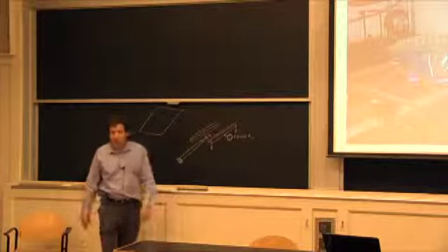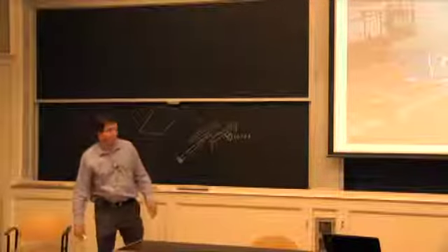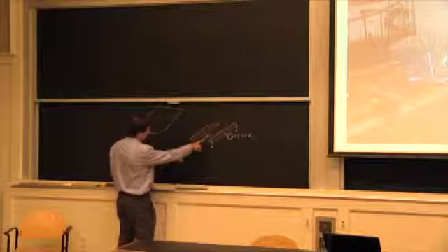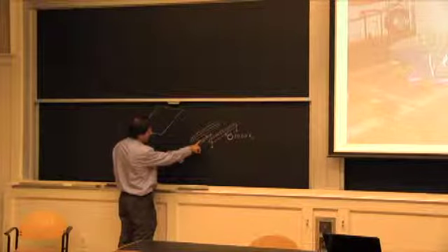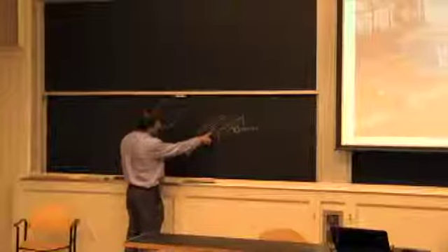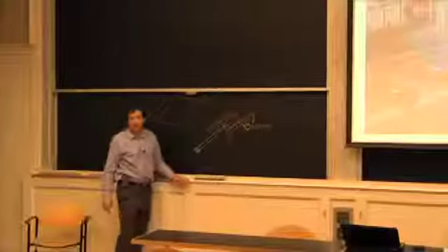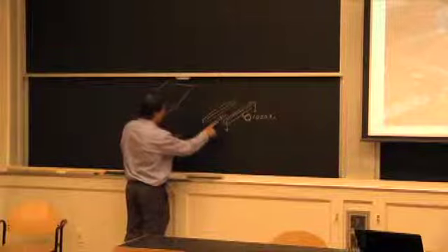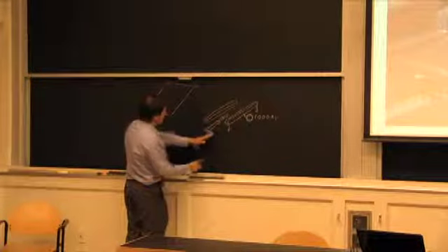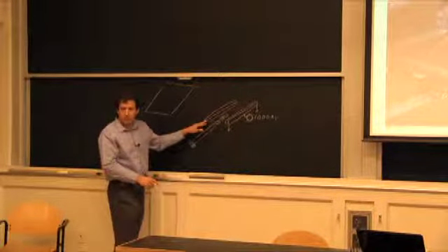The reason why I didn't get concerned with the overload is in this connection here, I did not have welds on the tension side. I designed my connection so essentially this member was sitting under the cross member and the welds were on the compression side.